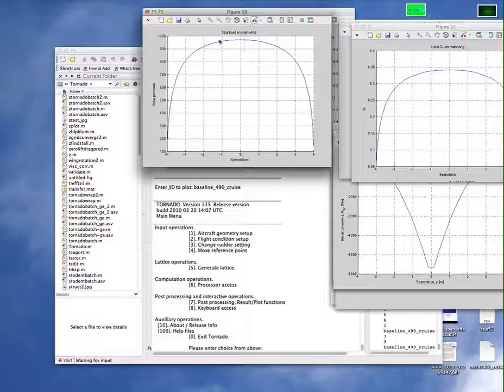It's this integrated force that becomes the bending moment, and you can see how the bending moment adds up. As you move away from the root, you're adding force times distance, more force times distance. That's the integrated amount. You integrate under the area of this curve times the distance from the origin, and that's your bending moment. So this gives you essentially the load distribution on the wing. This load distribution we want to be elliptical. This is the span load distribution, and it's not elliptical for this wing. So we're done with this wing.